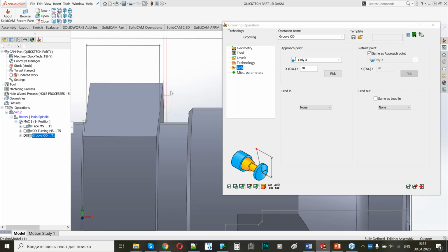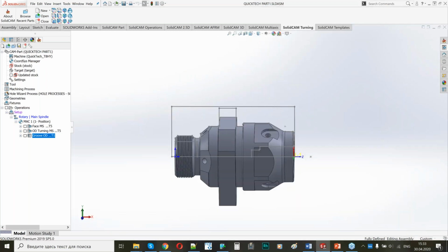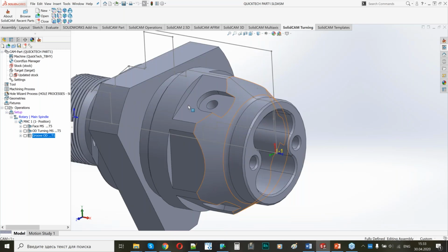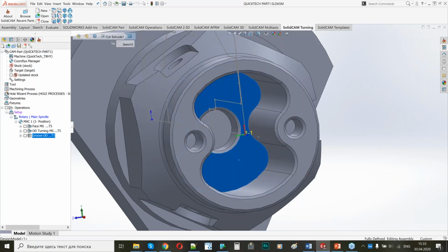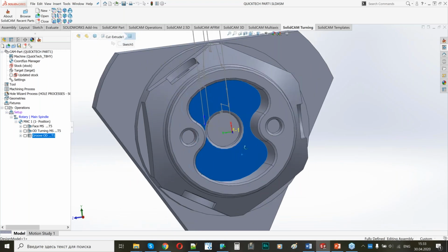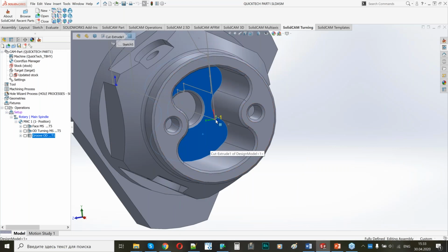I will start from milling the facing elements first, and then I will go to the radial elements. Here, for this deep pocket, I would like to use an iMachining operation, but it will be easier for the machine and for the tool, and I will save cutting time, if I first perform a drilling operation, and then use my hole to lead in my mill during the iMachining operation.